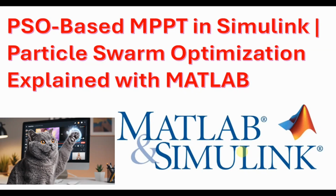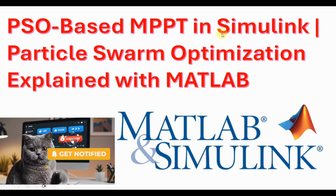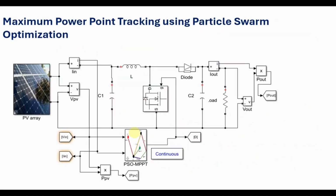In this video, we will study a particle swarm optimization-based maximum power point tracking algorithm, also known as PSO MPPT, implemented in MATLAB and Simulink. We will first understand the basic concept of maximum power point tracking, then explain the particle swarm optimization algorithm and its mathematical equations. Finally, we will move to Simulink and examine the complete PSO MPPT implementation, including the initialization process, particle movement, power measurement, global best selection, duty cycle generation, and PWM control.